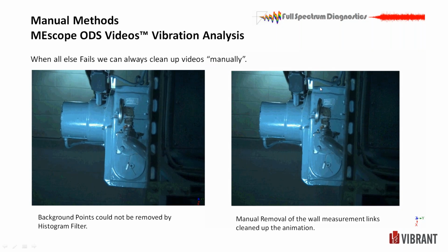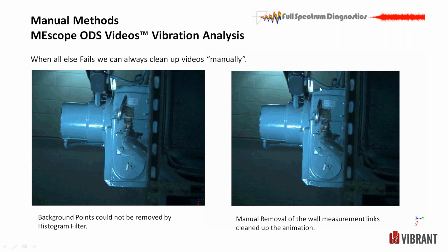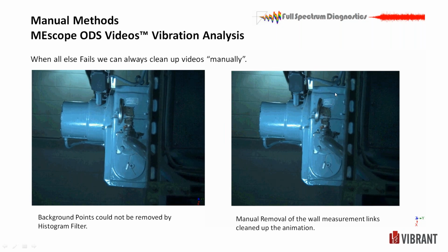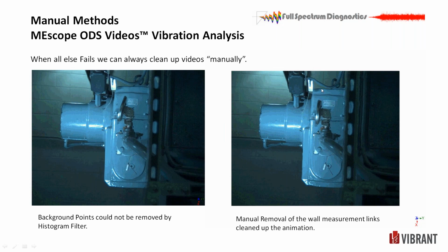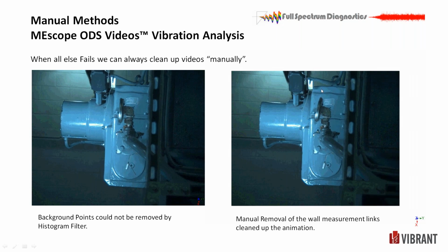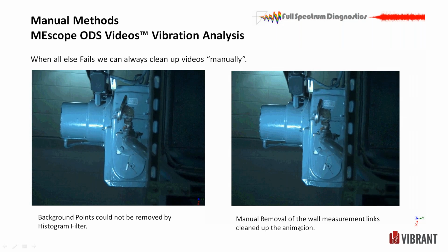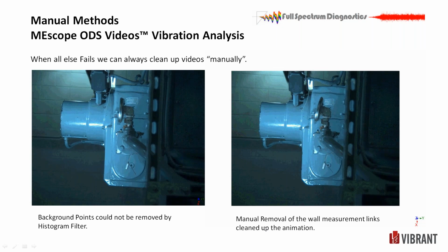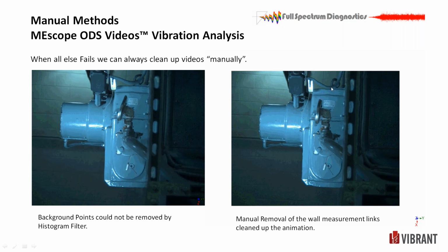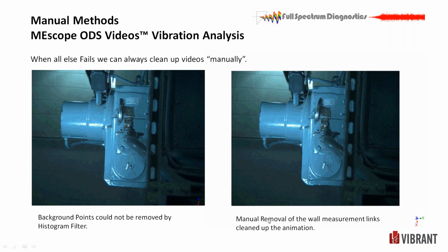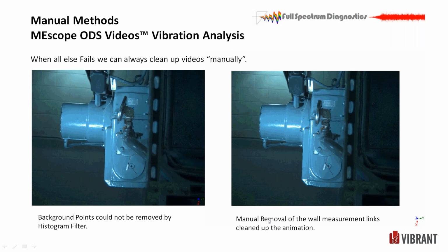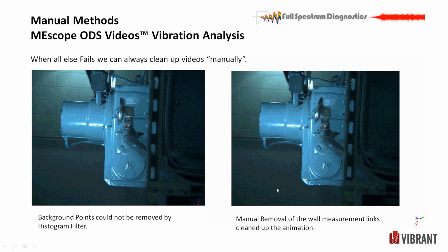While I was on site, I took an accelerometer and made a measurement on each bearing housing in X, Y, and Z directions. And I made that right here. And the data that showed up in the video analysis, it was in displacement, so we had to convert it to velocity. And it was almost identical to what we measured with an accelerometer. Pretty nice correlation.